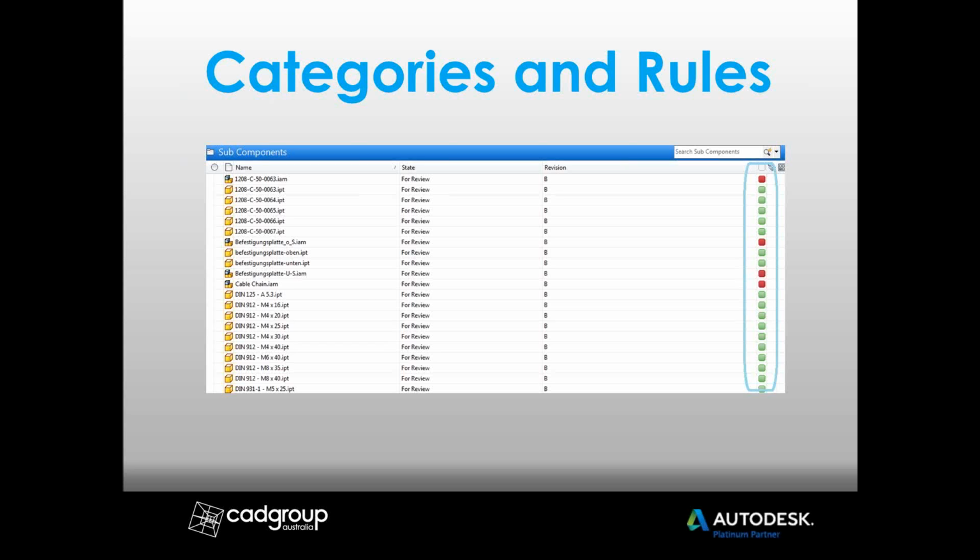When you link this in with rules, rules allow you to automatically categorize a file based on one or more file property values. This gives you the ability to assign a category when a file is added to Vault using Vault Explorer or the CAD add-ins from Inventor, AutoCAD Plant, AutoCAD Electrical, and so on. Now, rules work a bit like the advanced find workflow in Vault, in that you can specify a list of conditions to be met based on property values, be that user-defined values or system property values, or based on a file name when the file is added.